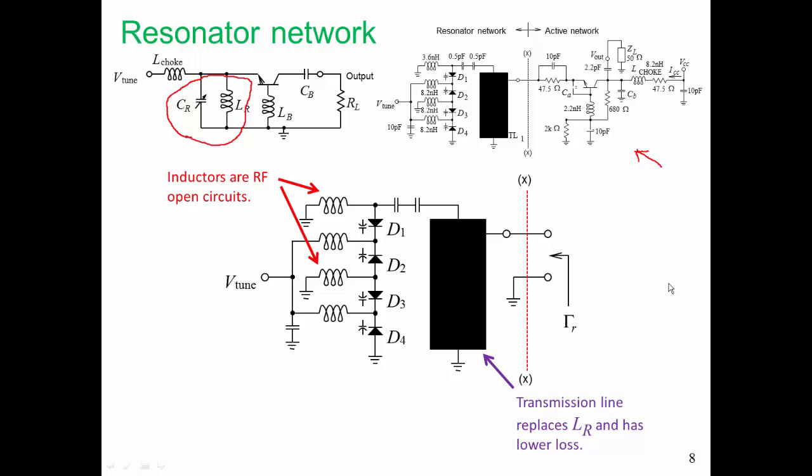This is a fairly low impedance line. That's a microstrip line. What is shown here is some indication that the width is very wide, so it's going to be a low impedance line. Another characteristic is that we tap the transmission line. We do not go directly in at the top of the transmission line. This provides a little bit of impedance transformation.